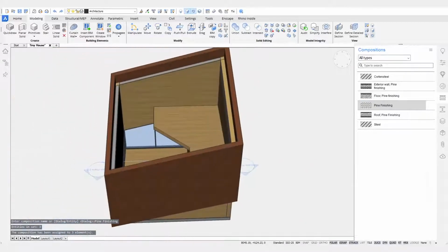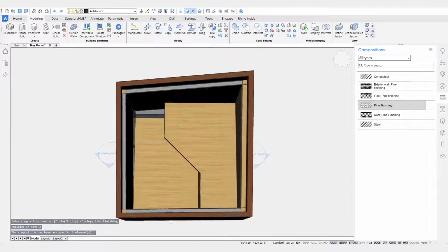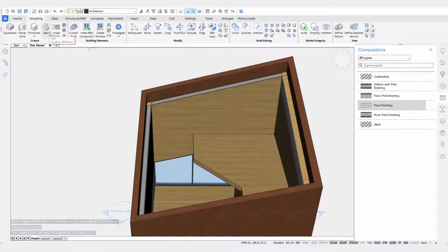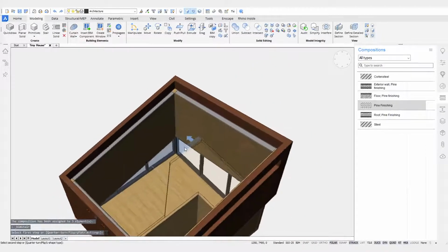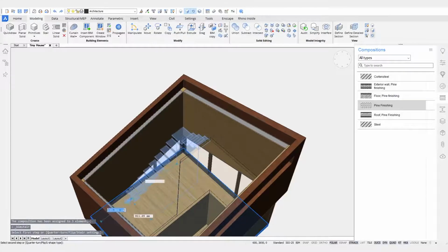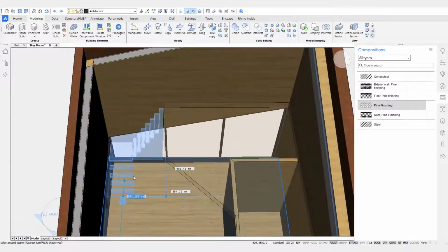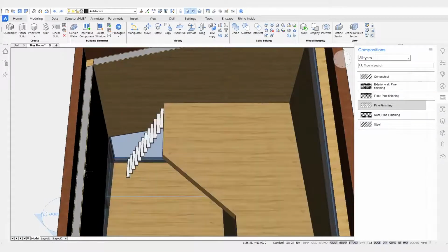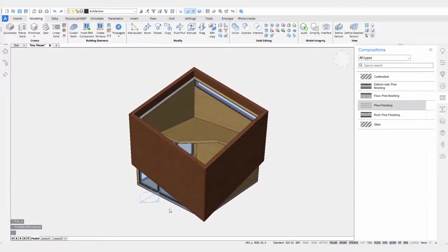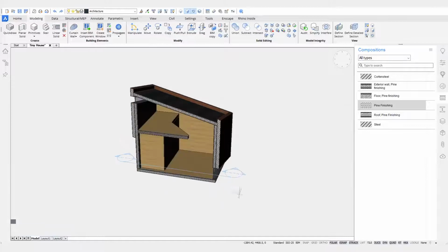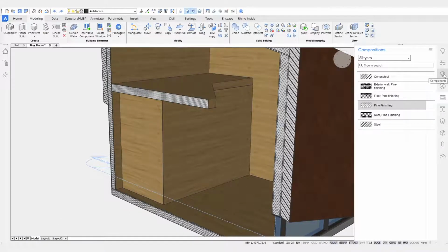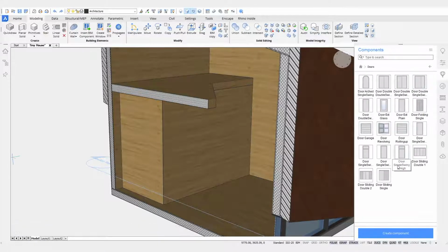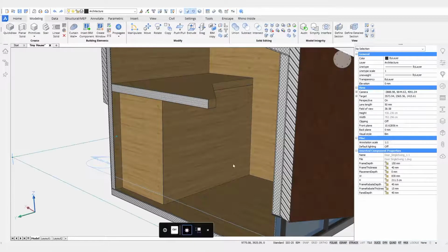And if we want to be able to get on top of this mezzanine, of course, we would need a stair as well. So I can use the BIM stair tool for this. It snaps to this edge here. Already got a preview. But actually, because of the limited space in this building, I'm going to use more of a ladder instead of a staircase. So just a very steep staircase in this case. And obviously we need a way to get into the bathroom as well, so I'll use a library object, a door, to get inside there.